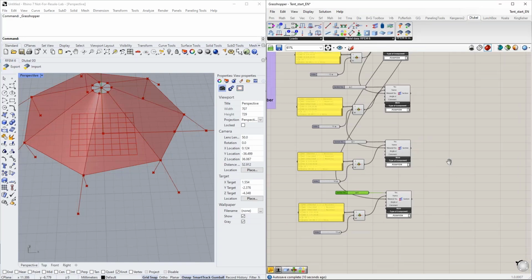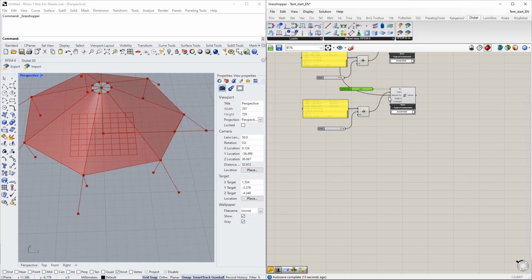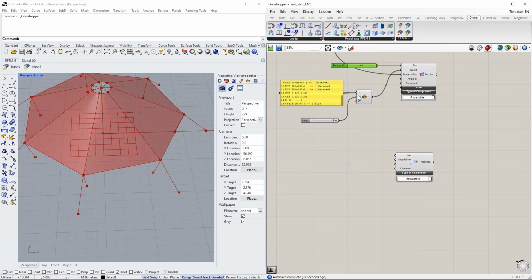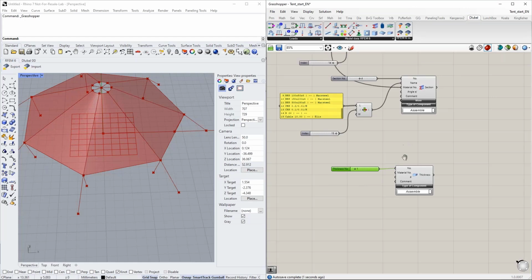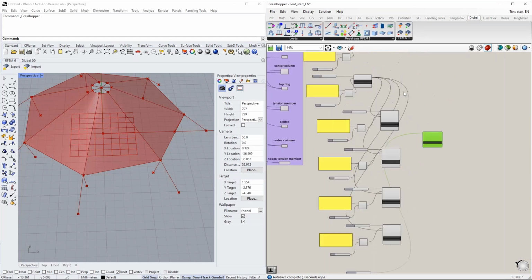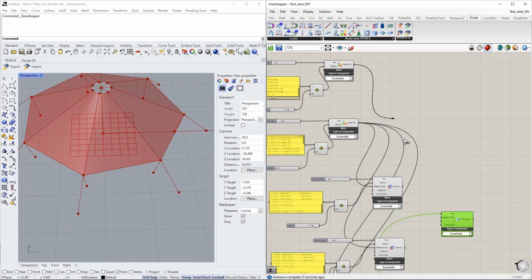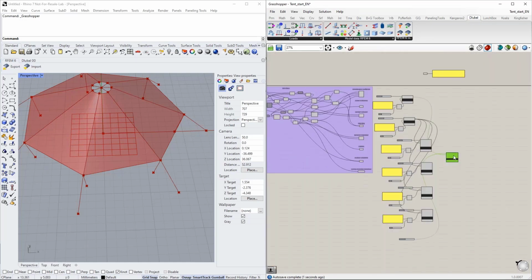The next step is the definition of a thickness, the thickness I need for my membranes. A surface needs to have a thickness assigned to it. This is the new RFEM 6 logic. And therefore I'm creating a thickness here with this component. Quite easy to use. Copy paste the index number, using it again, and then the material number. This is then material number 1, the PTFE material.